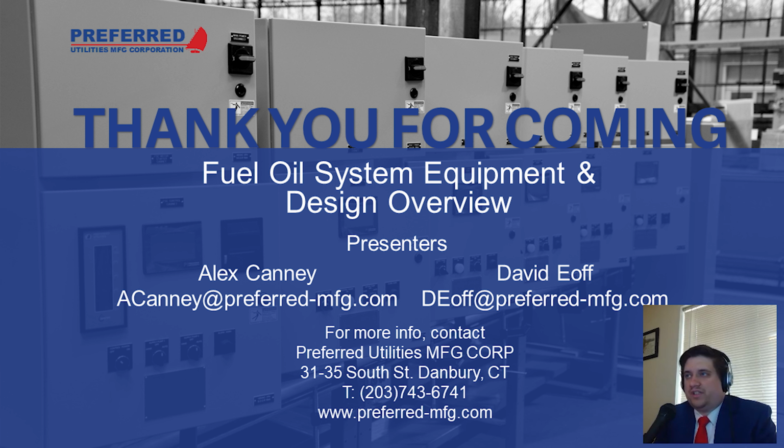And if you were with us last week, that's another reason why on a packaged pump skid, it's important for the transfer pumps to have a separate relief valve, so that if the pumps are deadheaded, we can bring fresh fuel through that pump head, because it not only moves the fuel, but it also uses it for cooling and lubrication as well.